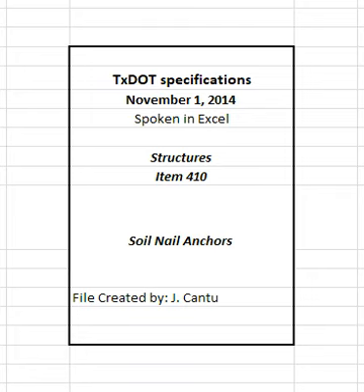3. Equipment. Furnish suitable equipment to drill the holes to the specified diameter, depth, and line. Provide a drill rig with an articulating head in the vertical plane and continuous flight augers. If an auger becomes worn to the degree that the drilled hole is less than the required diameter, remove the auger from service until it is repaired and can provide a hole of at least the required diameter. Return the auger to service once it is repaired and can provide a hole of at least the required diameter.